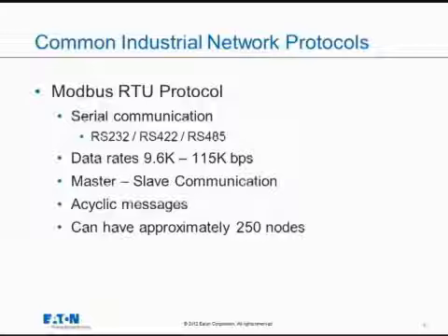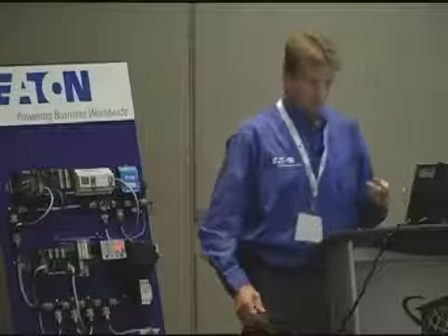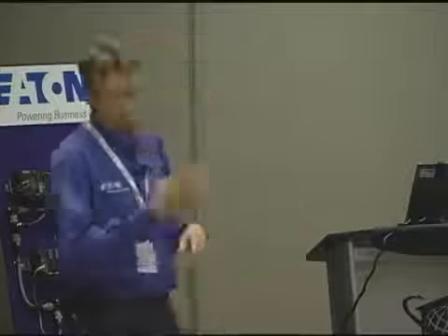It uses acyclic messages. What acyclic means is unscheduled messages. When we're talking messaging, we can have unscheduled or scheduled. Unscheduled means I'm a master, I make a request, I get a response. And then I can do some other things. And then if I need information, I'll make another request. I'll get another response. Cyclic messages are scheduled. And what that means is you ask for that same data all the time in a scheduled manner.